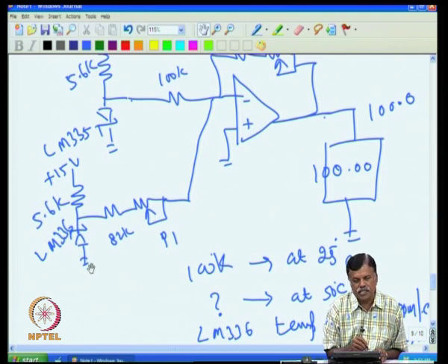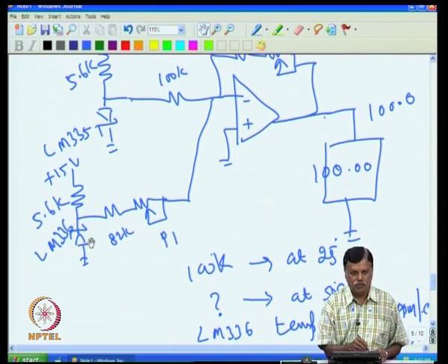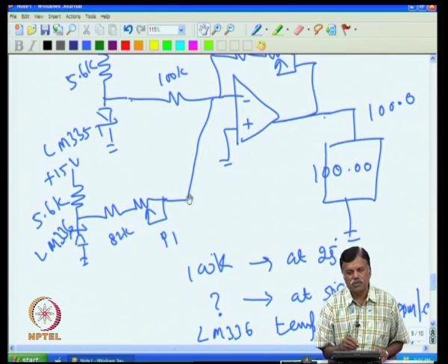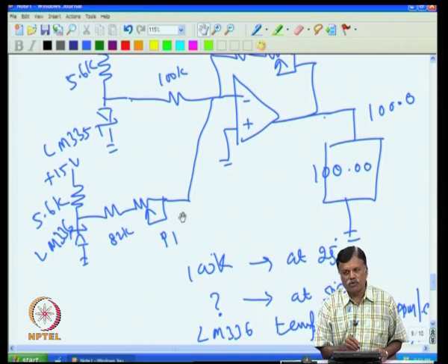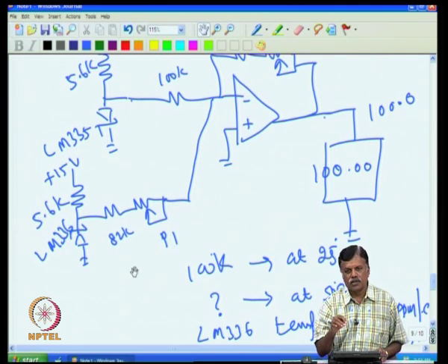So, obviously for industrial measurement or for industrial grade equipment, I have to assume that the temperature changes from minus 20 degree to plus 80 degree, because even at noon, if the instrument is mounted in the open field, and if you go and touch the instrument at noon, that instrument will be very hot. So, you have to take it as industrial grade working environment up to 80 degree.